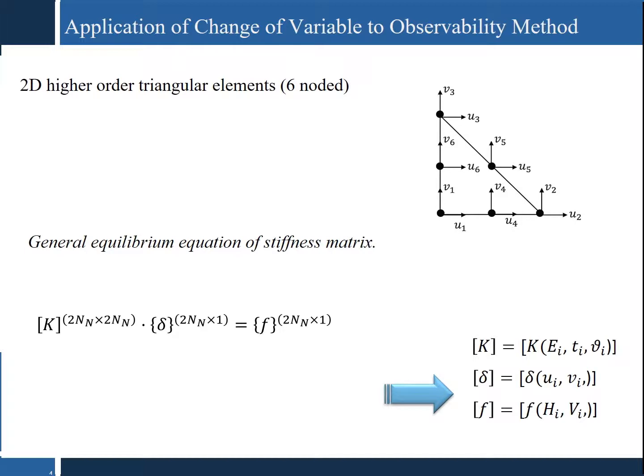Triangular elements are one of the best elements that can be used for modeling of irregular boundaries and have been used extensively for continuum stress analysis. As shown in the figure, quadratically interpolated triangular element has 6 nodes, 3 at each vertices and 3 nodes at midpoint of each side. This element is very useful in modeling of geometries that the use of 8-noded quadrilateral element leads to undesirable deformation and makes some problem in Jacobian mapping.